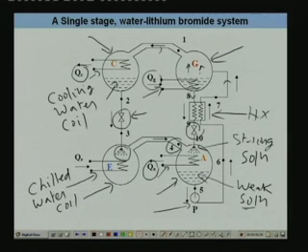As a result of it, since evaporation is endothermic, the water that is entering into this gets cooled. So ultimately what you get out of this is cold water. That is nothing but your refrigeration effect QE. And during this process, liquid becomes vapor, and this vapor goes to the absorber, and thus the refrigerant cycle is completed.